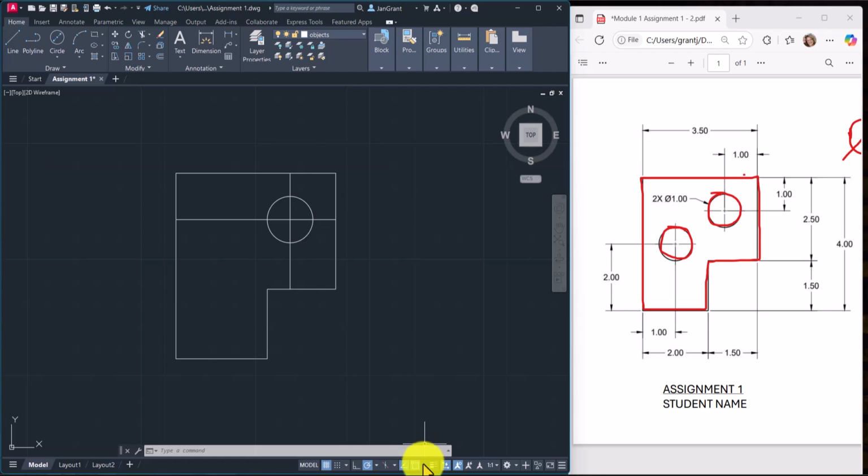Now going back to that intersection, those object snaps, let's take a quick look at those. At the bottom right corner, make sure that it's still on, but there's a blue icon right there with a box in it and another little box. That's object snaps. Click on the arrow to the right of it, and you'll see all of the object snaps. Now, I have way more on than you do because once you put them on, they will stay on. And I believe it's something like that as a default. So the ones we want to make sure that we have would be the endpoints, the centers, and the intersections. I like to put intersections and extensions. So you can check and uncheck those to get those object snaps.